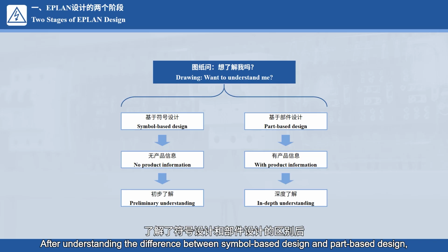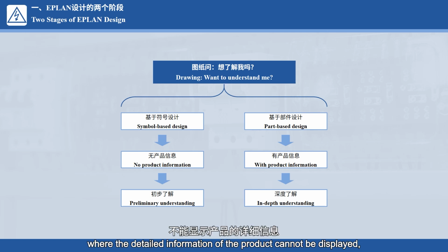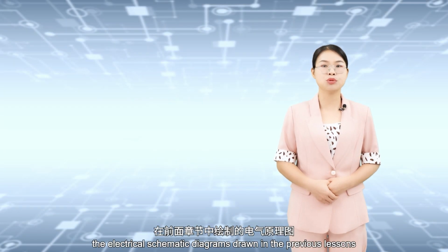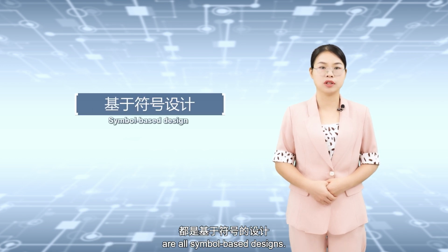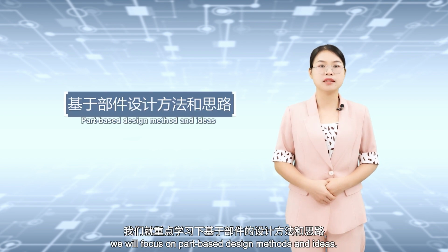After understanding the difference between symbol-based design and part-based design, we can easily judge that when doing design at the preliminary stage, where the detailed information of the product cannot be displayed, the symbol-based design method can only be chosen. When designing at the production stage, we need to provide detailed product information, so a part-based design method must be selected. At this point, we should be clear that the electrical schematic diagrams drawn in the previous lessons are all symbol-based designs. In this lesson, we will focus on part-based design methods and ideas.